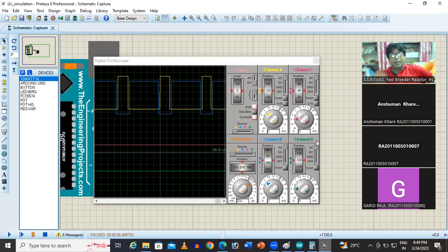But if you want a certain value of the PWM frequency, anything, for that this technique is not sufficient. For that, you have to use another register called the input capture register, ICR. With that only I taught them, because that PWM frequency is needed always customized in the case of resonance.